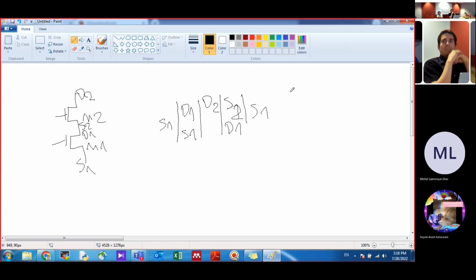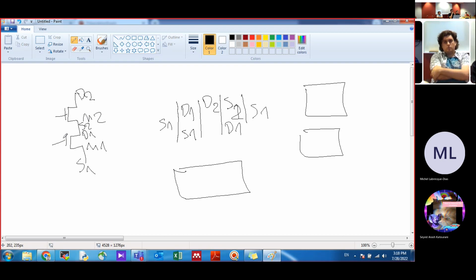It's like instead of layouting two big transistors, it's one transistor, as a cascode. That way you can shrink a lot, almost a third of the size, since you share the drain and the source. It is good, for example, in 28 nm, where we have those big guys.